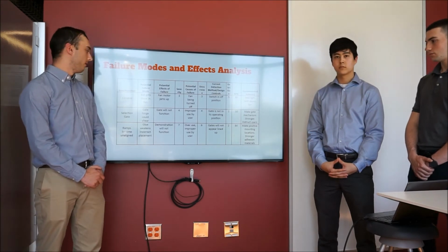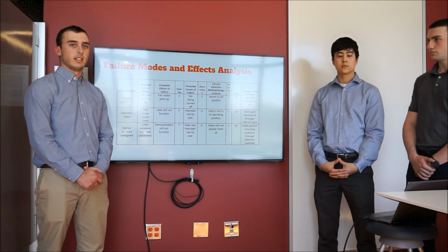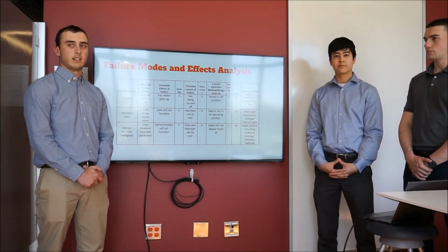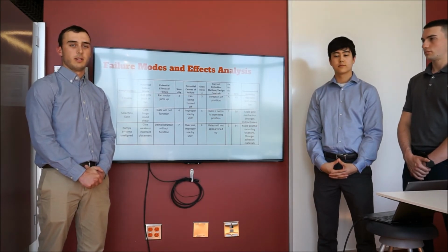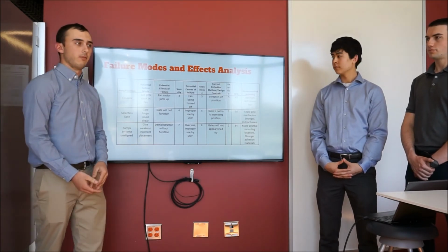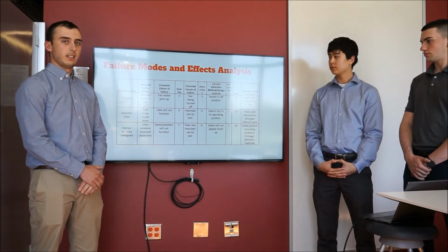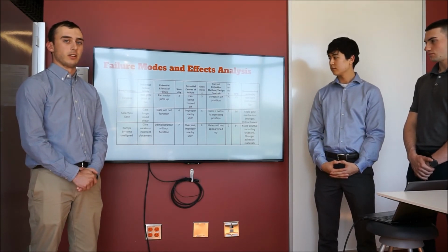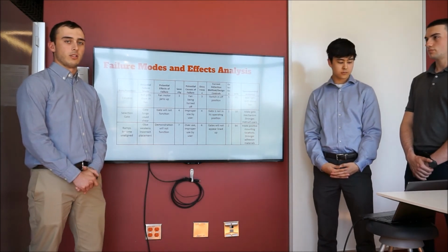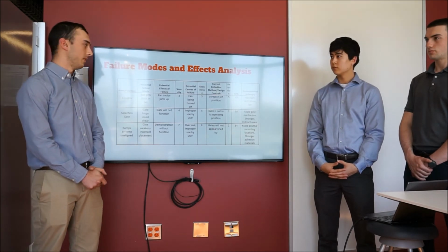Our second most prevalent failure would be the elevator. With our current design, we realized that the ball could get stuck in the fan. This would cause the demonstration not to work and could cause damage to the fan. It could also be dangerous for anyone trying to clear the fan with their hand when the fan was still energized. Ways that we decided we could fix this were by putting a grate over the fan so that if the fan were not supplying enough flow or was off completely, the ball would rest on the grate and not go down into the fan compartment.